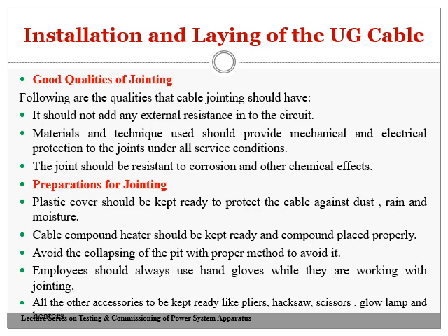Not the complete cable, only the part which is punctured should be removed from the trench and brought outside, and that area should be covered with a plastic cover, so that the cable ends where you have made a cut to have the joint are protected against dust, rain, and moisture.